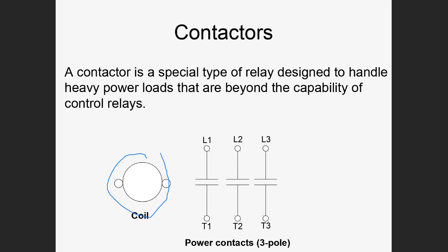And it usually switches three-phase. So if you're working for, let's say, GE or Procter & Gamble in a factory environment, and your PLCs can switch an industrial motor on and off, it's probably going to be three-phase, and you can't take the three-phase motor and hook it directly to the PLC.